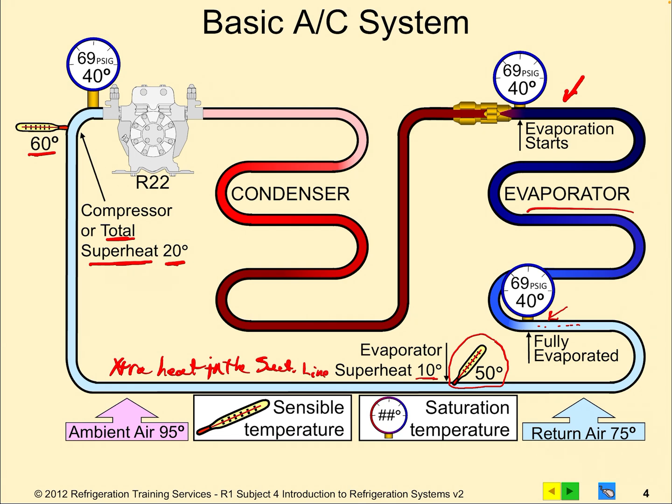All right. So we are up to the compressor right now. So we've done the low side. Now on the high side, just like the previous system, we had 278 psi, 120 degree saturation temp. So the 278 psi really just told us what is your condensing temp. What is the temperature where the refrigerant will either boil or condense at, is what's going on. So that's kind of the deal with that. We left the compressor at 175 degrees. It's very superheated because our temperature is way higher than the condensing temp, and that's so typical.